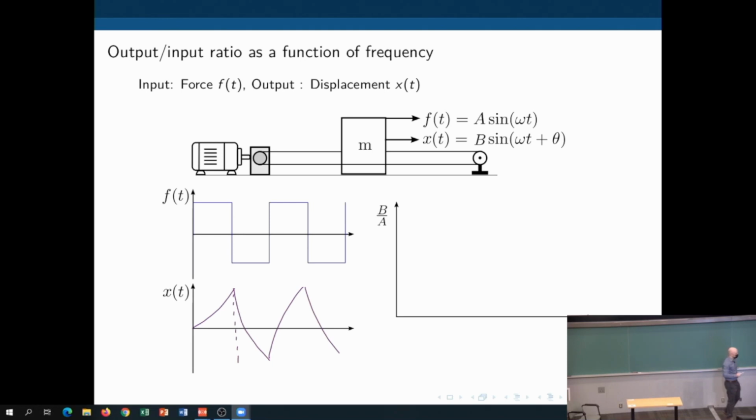unlike the speed. So what do we see in the response here if you now plot the position over the magnitude of the force? Well, we should see something that decreases over frequency, because as we increase the frequency, we are making it travel back and forth faster, and therefore we'll reach a lower position. We are not giving it enough time, or less and less time for it to travel in one direction.